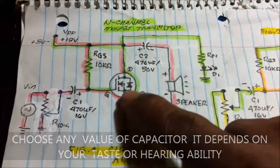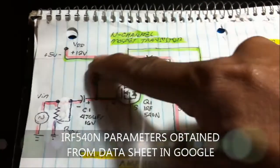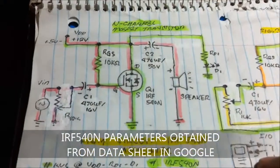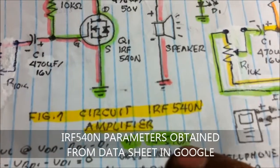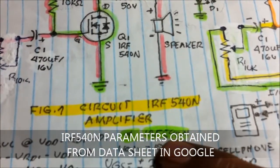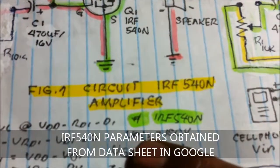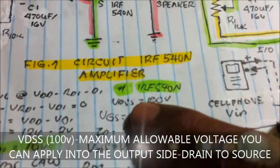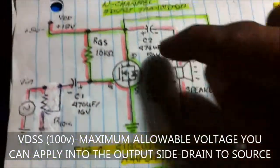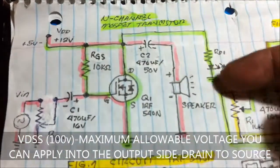So in here, why is it that the gate is open once you apply 12 volts? There are certain parameters used in this type of amplifier, this IRF540N. We have here voltage drain to source, VDS. What is that VDSS in the datasheet? 100 volts. That is the maximum voltage you can apply to the output.